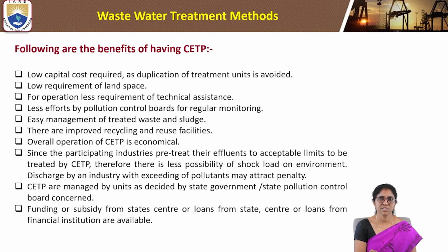So what are the benefits of CETP? Low capital cost is required for the CETP, and duplication of treatment units is avoided. There is a low requirement of land space, and for operation, less technical assistance is required. There are fewer efforts by pollution control boards for regular monitoring. There is easy management of treated waste and sludge, and improved recycling and reuse facilities. The overall operation of the CETP is very economical.